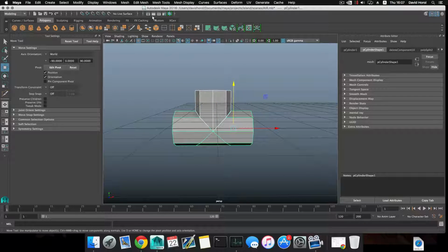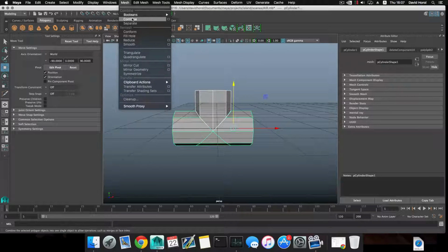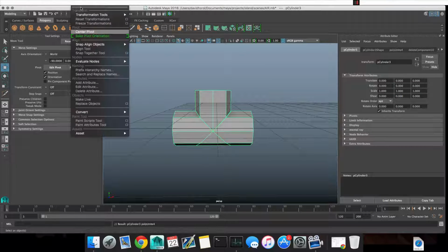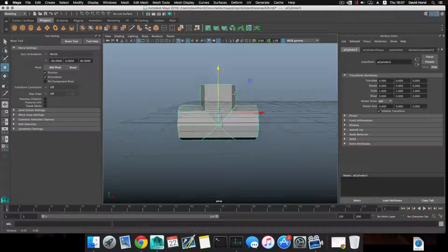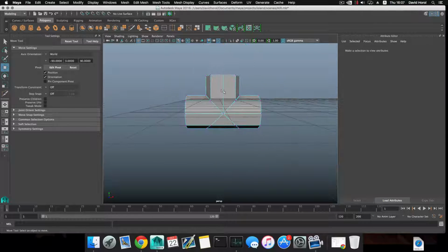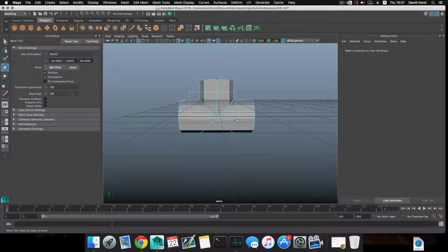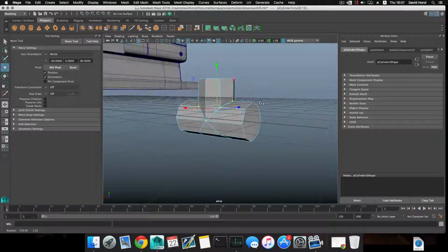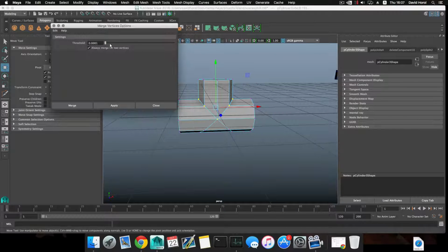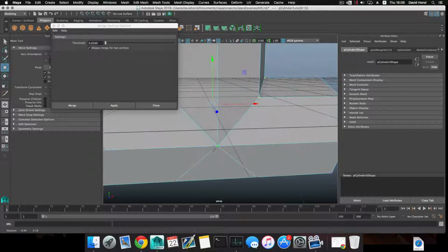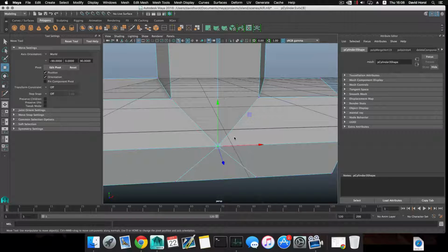Alright. You can grab both of them. Mesh, combine. Modify, center the pivot. Second. Back. I'm gonna grab these, all these connection points. And I'm gonna do sort of an aggressive merge here. So let's pump this to 0.0500, sorry. Apply. And let's see if this really worked.